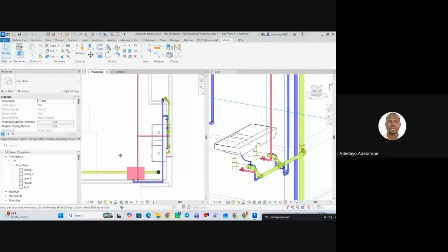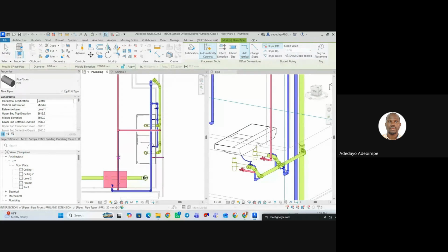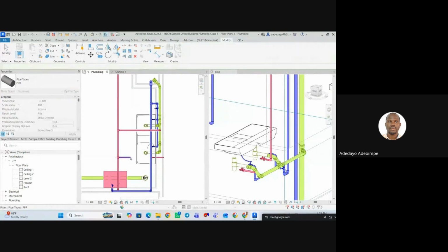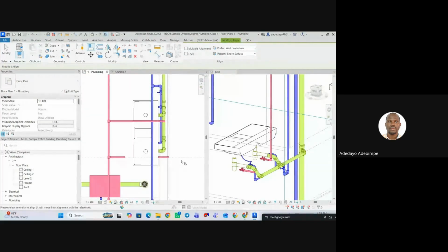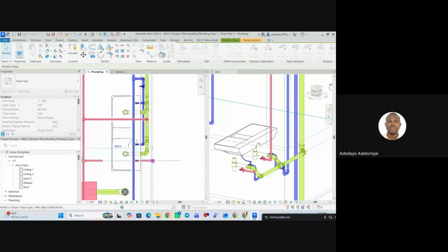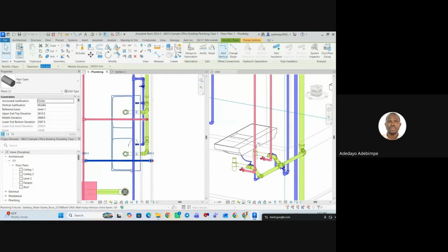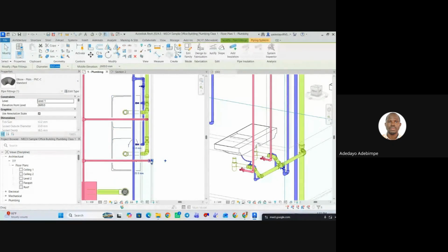Then go to my mainline pipe, right click, create similar, or I can press PI, draw out a pipe, then do AL to align the two pipes together. AL to connect them. Then I'll pick my pipe and draw it out to connect to the pipe supplying our angle valve. Then I'll move it back into position.